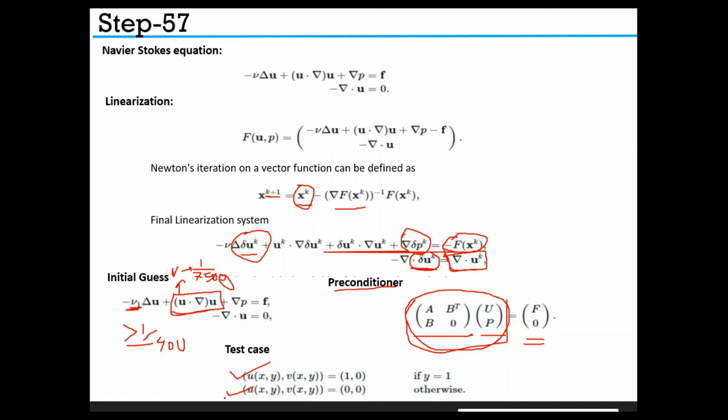So in the code we will apply the if else, and when we solve this problem, the error consists of nonlinear error, and the nonlinear part decreases with each Newton iteration, and the discretization error reduces with mesh refinement. So in this example, the solution from the coarse mesh is transferred to successively finer meshes and used as the initial guess. Therefore the nonlinear error is always brought below the tolerance of Newton's iteration, and the discretization error is reduced with each mesh refinement.